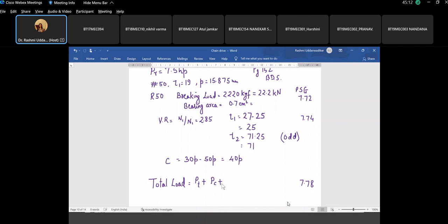And instead of the catenary action, this is talking about the tension in the chain because of the sagging of the chain. The sagging component is larger here because it is metallic and the weight is sufficiently large. So this is the sagging component. PT is the same as FT, and then this will be multiplied with the service conditions, K1, K2, K3, K4, and almost till K6 the service conditions are given. We'll take all of them one by one.